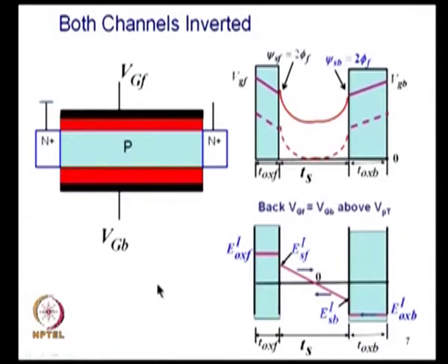Okay. Now, you have got a situation where I have applied, let us say, a situation where the oxide need not be the same thickness, but I can apply a large enough voltage so that the depletion layer from the back side comes up to the center. So now I can come from the front gate till the depletion layers merge, that is the situation. If the depletion layer were coming up to this point, the potential will be symmetric. Even for a thicker back gate I can do that, but the difference will be that the back gate voltage will be more, because more voltage drop will be in the oxide. So the drop from the midpoint to the surface on both sides is equal, but for the same field the voltage drop in the oxide will be more here.